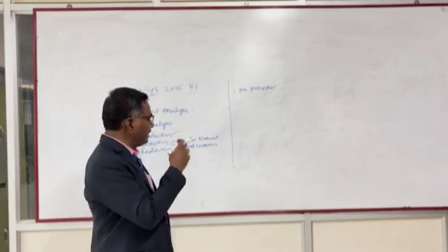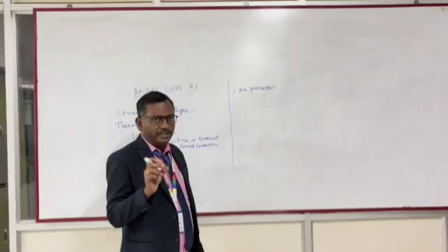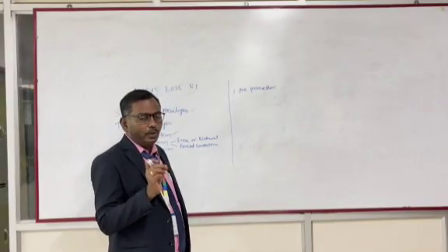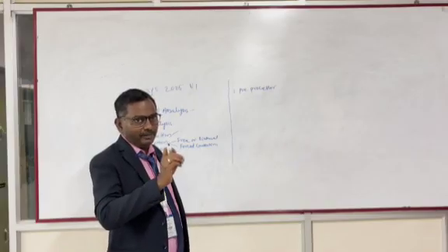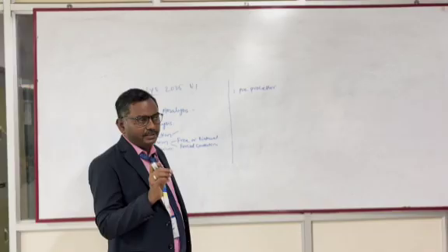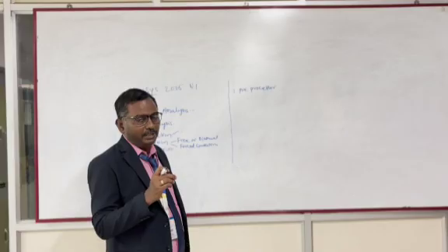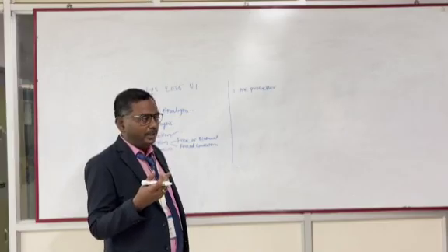So that is coming into the preprocessor. In the preprocessor, we have to define the element. First step, we are going to define the element, type of element.